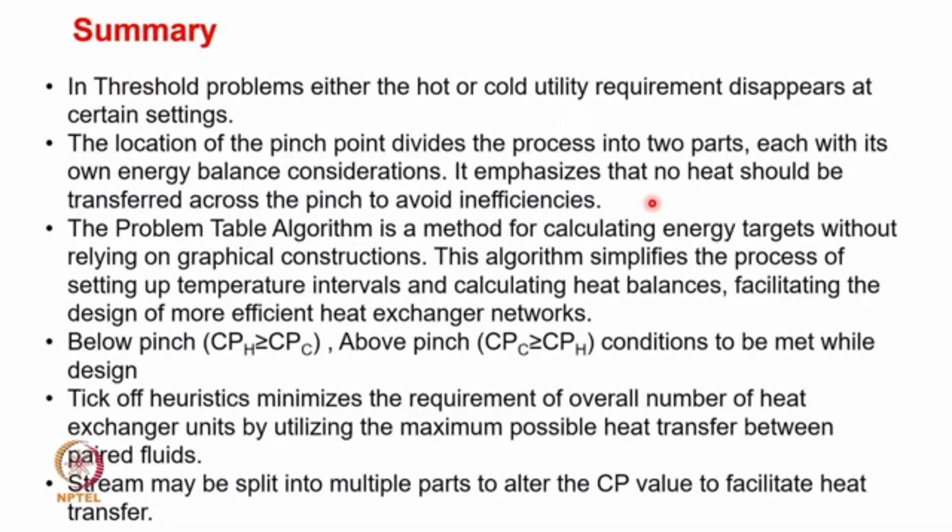And we have seen threshold problems where either the hot or cold utility requirement disappears, and the location of the pinch point divides the process into two parts, each with its own energy balance constraints, emphasizing that no heat should be transferred across the pinch to avoid inefficiencies.